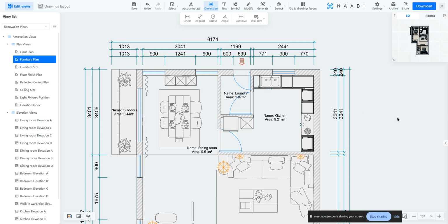Second thing is your annotations. Some organizations have a practice of mentioning the external finish of the shutter and the external elevation of the cabinet as IC and EC. Majority of the organizations have a practice of hatching the shutters to mention the difference, and they'll add a separate legend mentioning what that finish is. Some organizations have a practice of adding a leader for those finishes. They don't attach their shutters in the drawing. They add a leader for different finishes, right? So in the annotations itself, there are so many practices here.